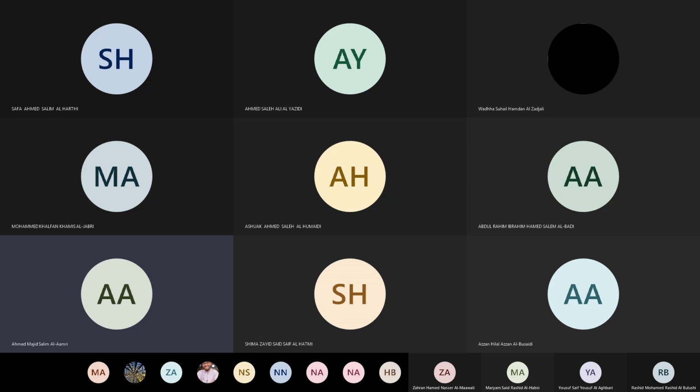So first, we need to bring our architectural and structural drawings, and you can see I tried to bring almost the same drawings, and you can see that they reflect each other. Whenever we have a position of a column here, for example, it reflects here as well. One thing you can notice is that there are extra beams where there are no walls in certain places. Like here, you can see that we don't have a wall, but the structural drawing reflects that you have a wall or a beam here.